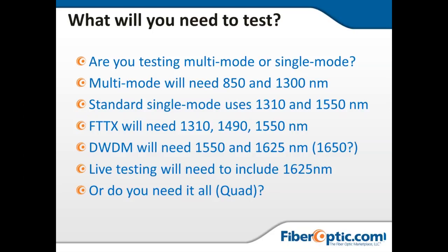So it's very highly sensitive and highly tuned. If someone was sending a signal directly down the fiber towards us, their power is so strong that it'll actually burn out the receiver. So we've got to make sure that we're filtering out power that is not the power that we're trying to measure. So if you want live fiber testing, you need to make sure you talk to your sales rep about that and make sure you get that put in there correctly.